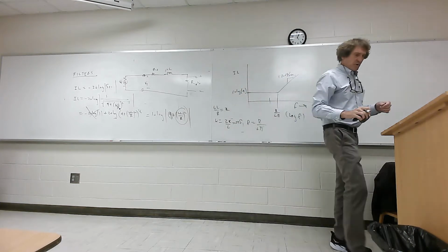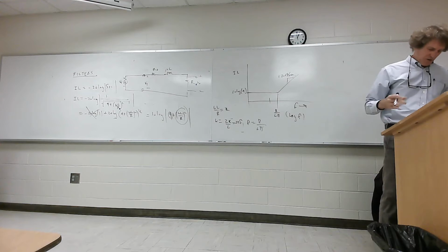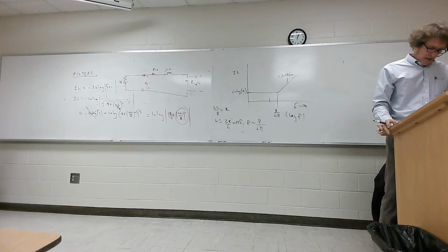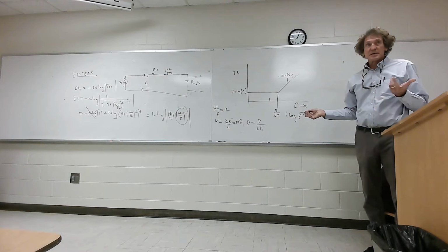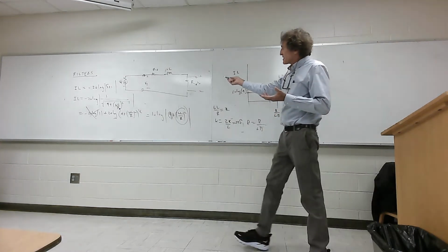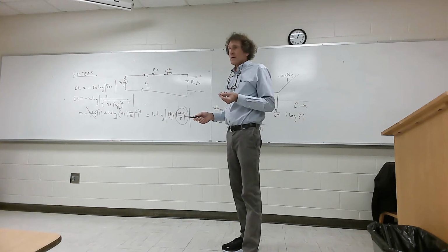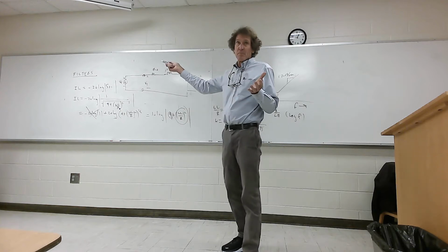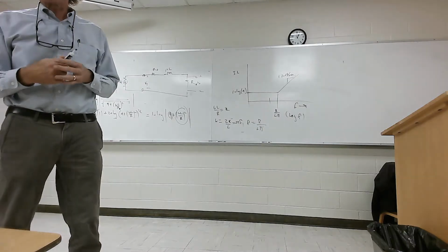Now, in his book, he shows you, on the next page, I believe it is, that plot done. He actually does the actual plot in MATLAB. But I want to make this clear. The real thing with these is if I give you something like this, and I wanted the insertion loss, you just simply do voltage division, output over input. Take that and just minus 20 times the log of that, and that's it.